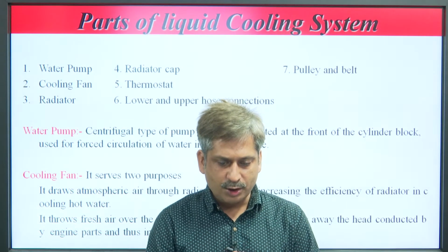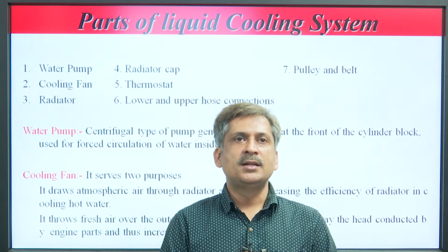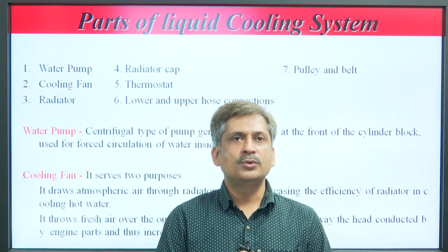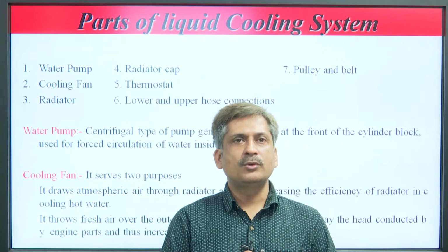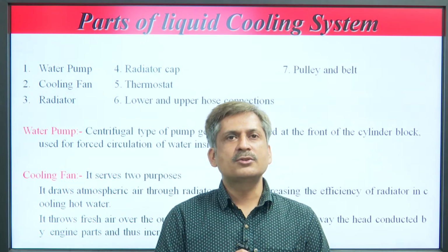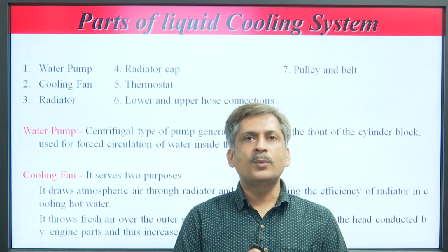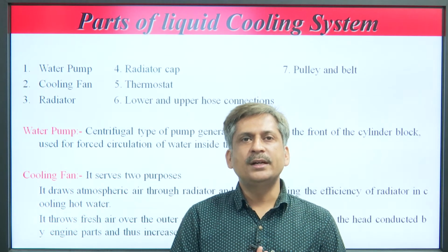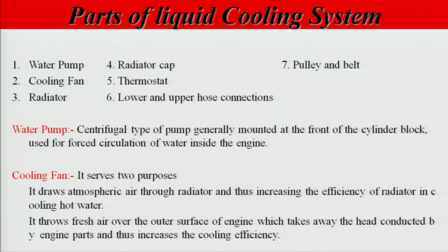Now, coming to the parts of the liquid cooling system. So, three major components of the liquid cooling system we have discussed. These are the water pump, cooling fan, radiator. These are the main components, and other components are also there, like radiator cap, thermostat, lower and upper hose connections, and pulley and belt. So, the water pump, you all know that it is a centrifugal type of pump, generally mounted at the front of the cylinder block, and why is it used? For the forced circulation of water inside the engine.